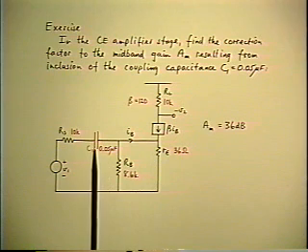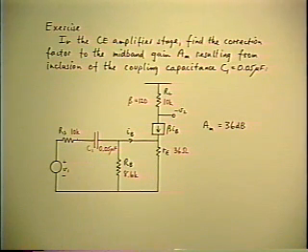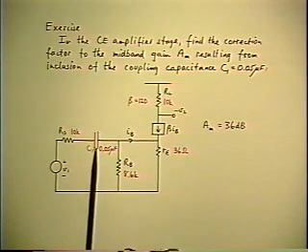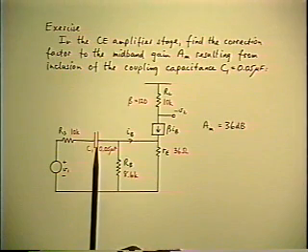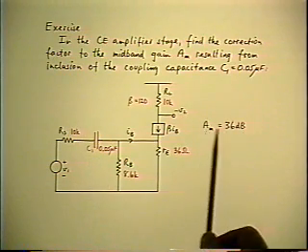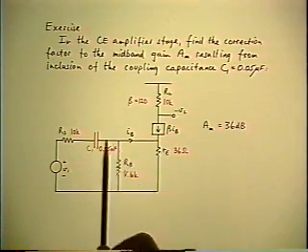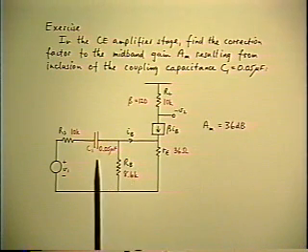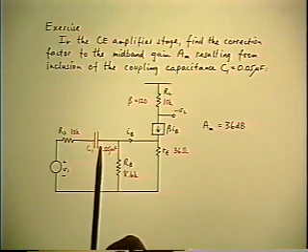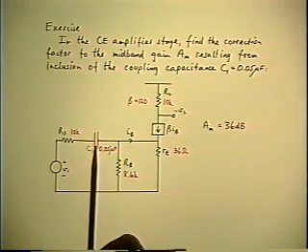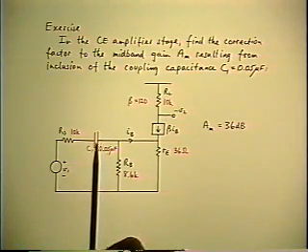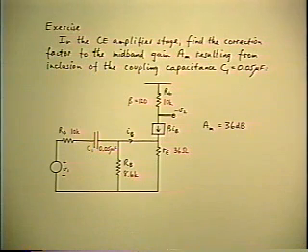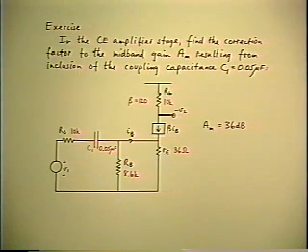But let's put the spotlight now on the coupling capacitor, which up to now we've taken to be an AC short, which leads to the same mid-band gain of 36 dB that we had before when C1 acts as a short. And so the problem now is we want to account for the coupling capacitor, so we treat it as an extra series element, whose reference value is zero impedance.